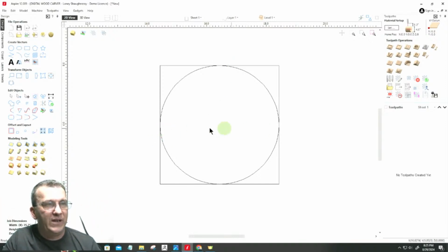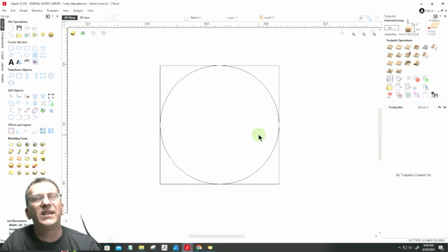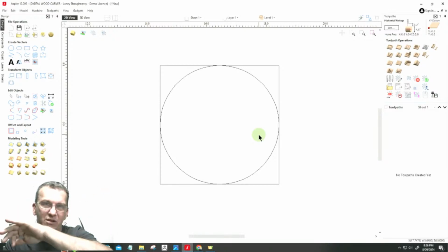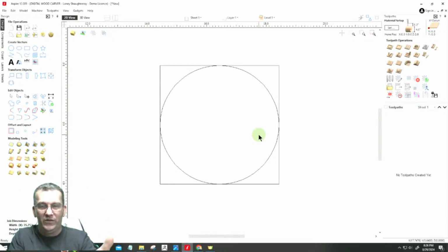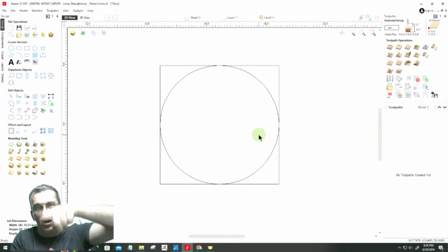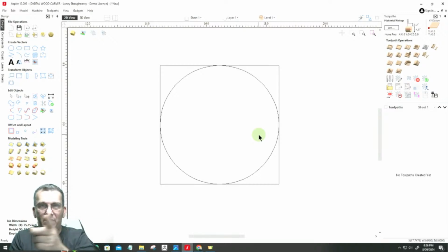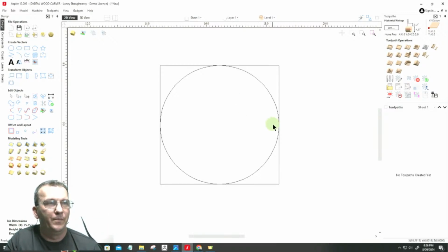So 3 15/16, or to give myself a little bit more room, I'm going to go 3 7/8. So I'll give myself a 1/16 of an inch on each side, because you're thinking now 360 degrees around, left side and right side, or top and bottom. When I'm measuring across that diameter, I need to account for it.